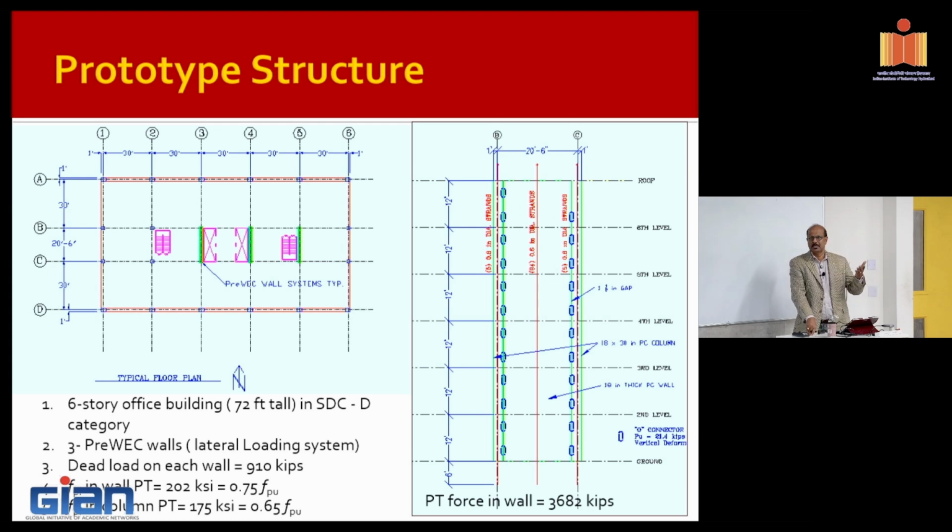So the thing you should expect is, maybe it's going to displace more. If it's going to displace more, by how much? Maybe it's going to go through more cycles than this one, because this one has more damping. So if that's the case, how many more cycles? Is that going to cause low cycle fatigue issues to the structure? Those are genuine questions to ask.